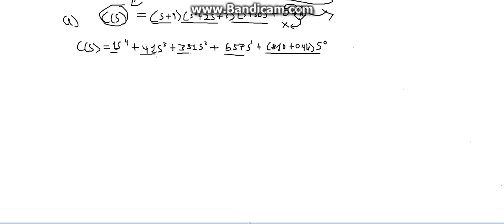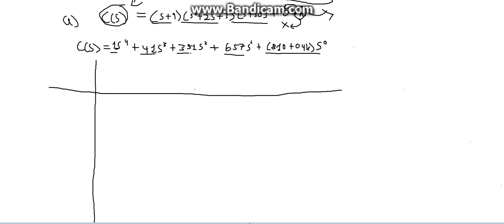So you gather each and every polynomial here, and each and every term in front of them. Then you look at the highest order polynomial, which is 4. 4 means we begin our table of Routh criterion. This is a table. Now you need to memorize this stuff. You create a simple 2 by 2 table, but in this form.